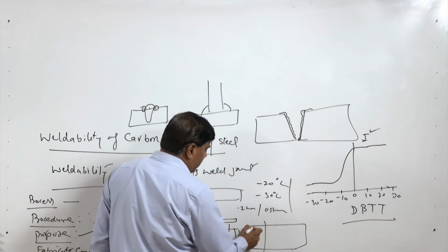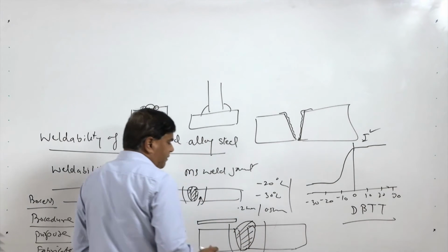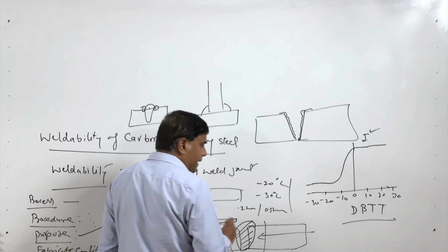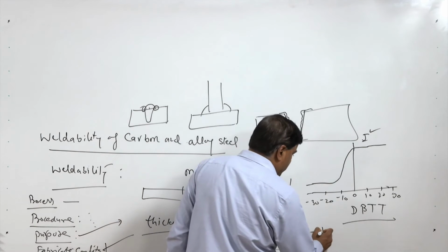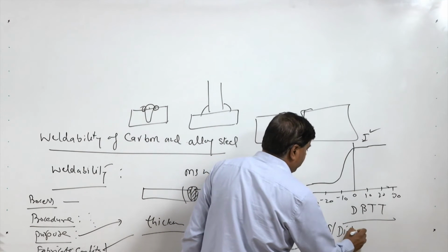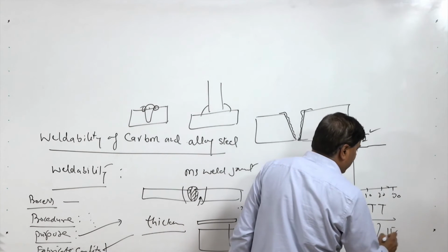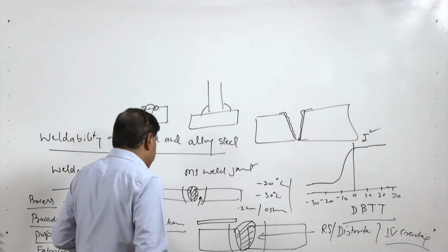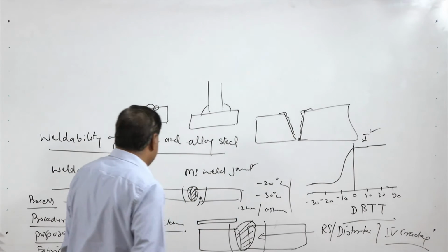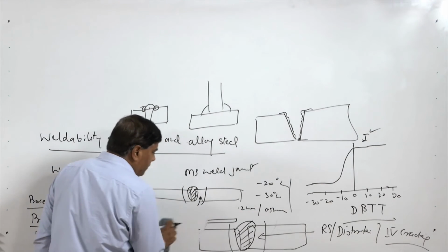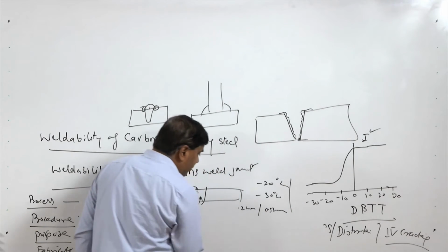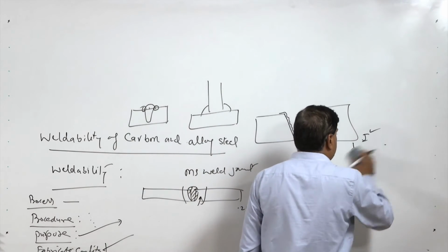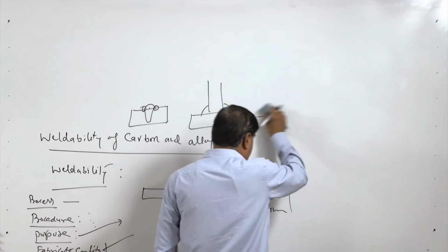What we see is that the heat affected zone developed due to multi-pass welding degrades the heat affected zone properties very badly, and sometimes this causes residual stresses, distortion, and type 4 cracking problems or reheat cracking problems. There are various issues related to multi-pass welding, especially in the case of thick welding. So both thin and thick can impose various kinds of problems even for a given metal, which shows very good weldability under a given set of conditions when thickness is neither too low nor too high.